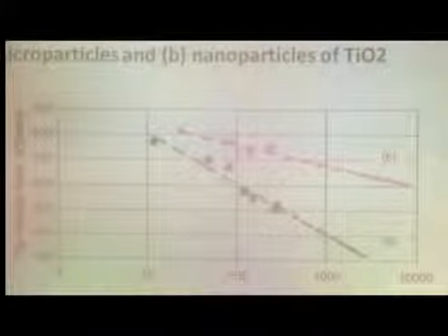And therefore, we might expect that we could generate a nanodielectric in which avalanches are substantially reduced, and therefore we might expect to see a reduction in electrical treeing. And certainly, work by Keith Nelson and so on, where he talks about voltage endurance, whereas in fact he's actually growing electrical trees in these materials, he's shown that with nanoparticles, the expected lifetime is much greater than with equivalent microparticles.